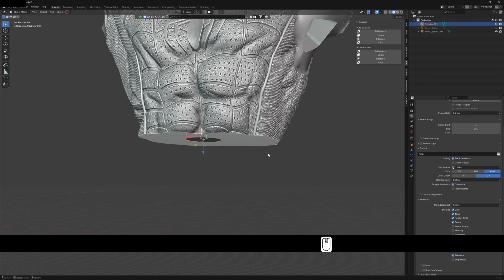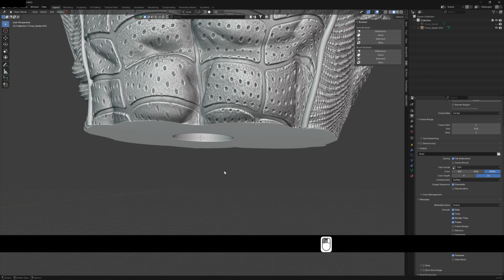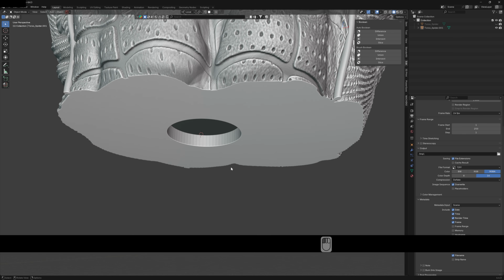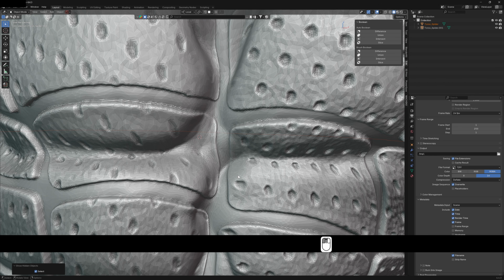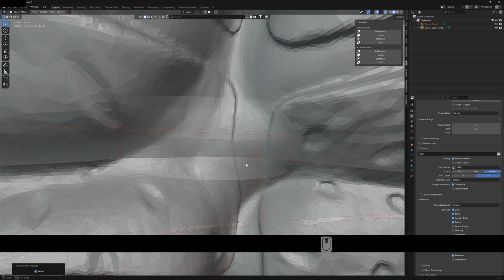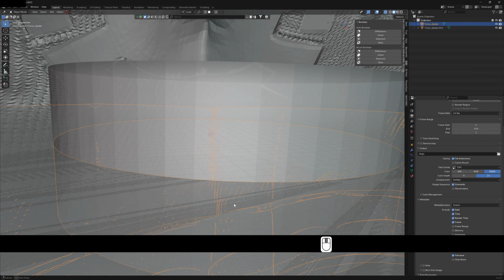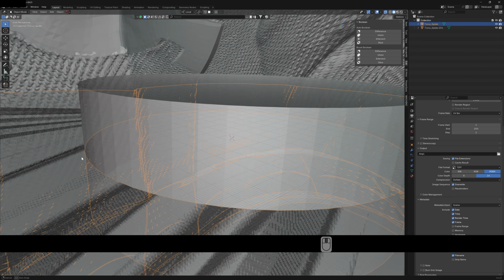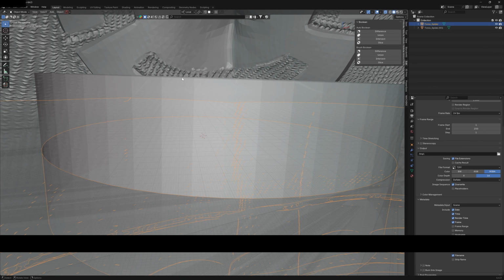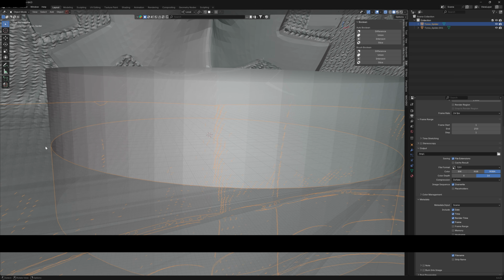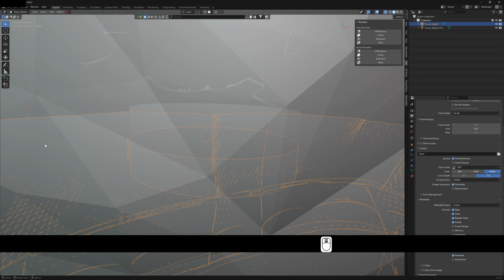Got the object selected, that's your cutter, your object you want to keep, difference, and then if my theory is correct, my teachings are correct, if I press Alt H to bring both parts together, go to X-ray mode up here, you will see that, there we go, both bits are exactly aligned perfectly. If I had not gone to local with the top part, it would have been shifted to the left slightly. So be mindful of that.